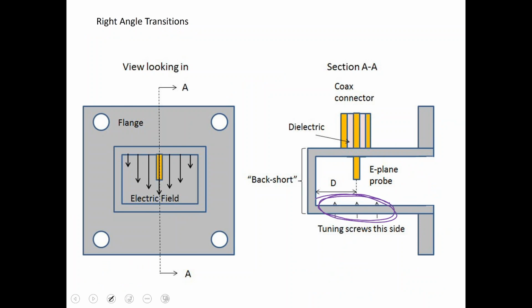These tuning screws are effectively making the waveguide act mathematically like a capacitance or an inductance. And using those, we can start to do some matching over here so that the field propagates forward and doesn't bounce back and forth in this direction. There are not many standing waves which should be created in that region.